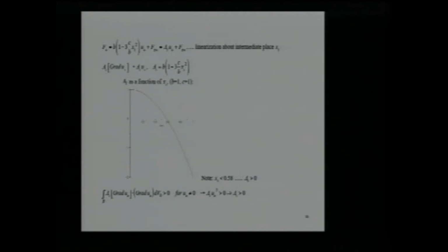It has a positive part and a negative part. And the Hadamard integral is replaced simply by AI, which is the slope of the restoring force curve, times U error squared, which must be greater than 0. This means AI must be greater than 0. Then the intermediate configuration will be infinitesimally superstable in this range, and it will not work in this other range.